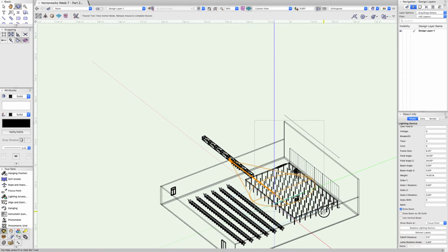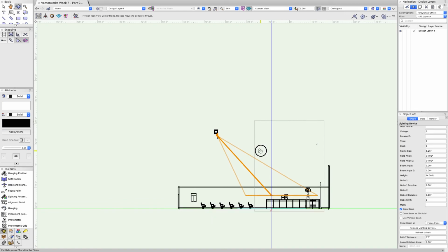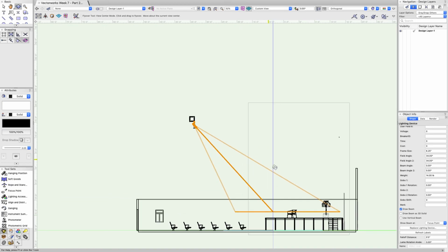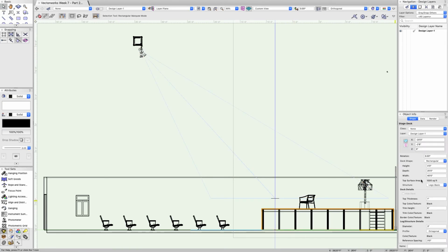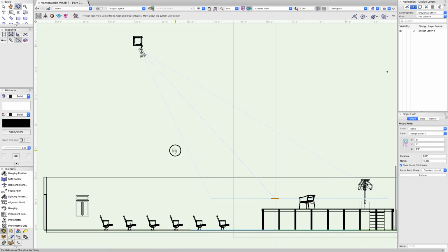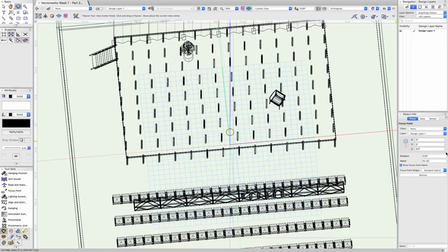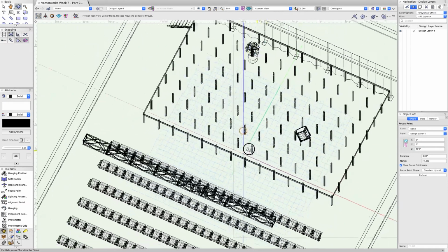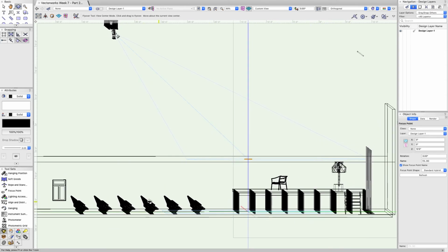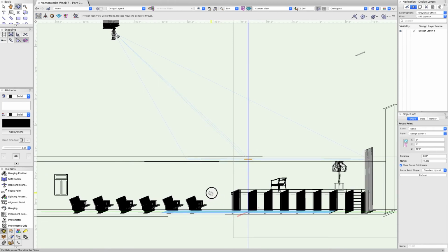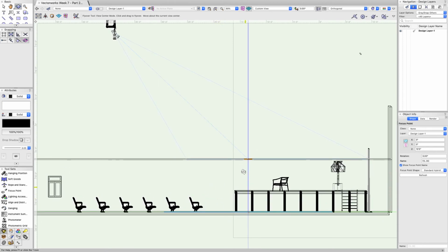And if you notice, it's not at 6 feet from the stage, it's at 6 feet from ground level. So for the focus points, you're going to want to hit the stage and say, okay, my stage is how high? 4 feet. So my focus point, which I'm going to select here, actually wants to be 6 plus 4, which is going to be 10 feet. Right, so now my focus point is 10 feet from the Z0, which is the floor of the room, but 6 feet from the stage level.